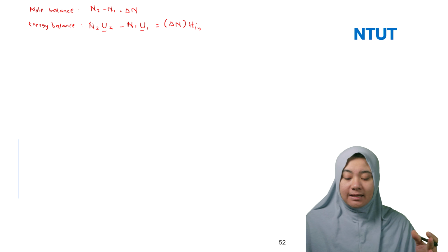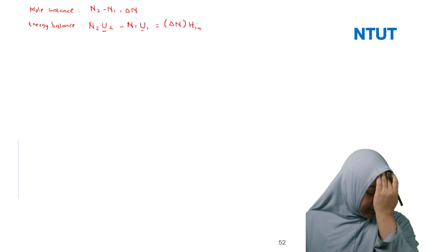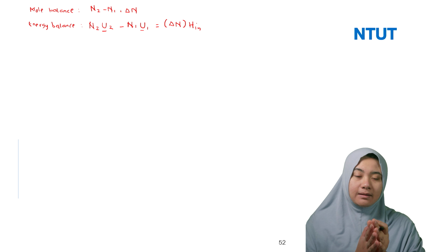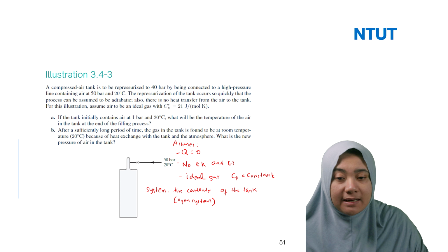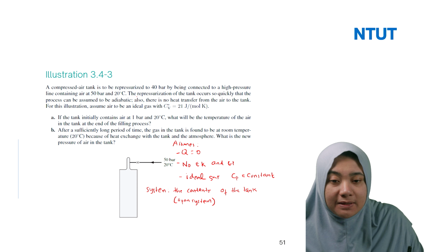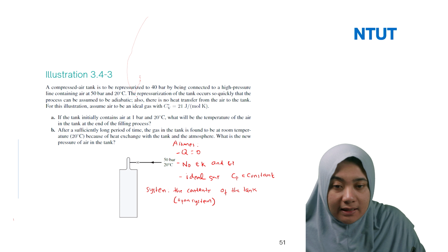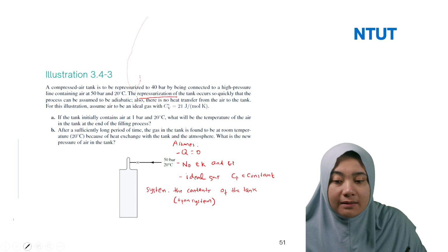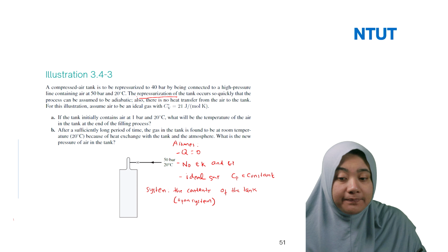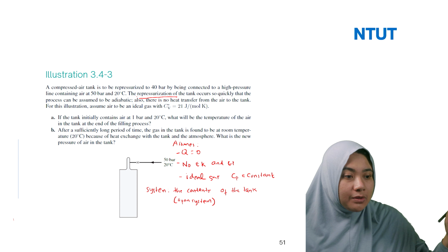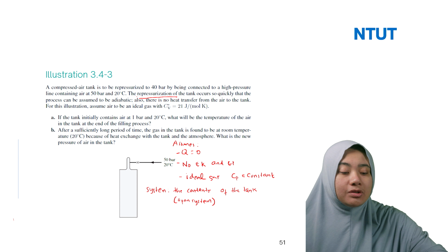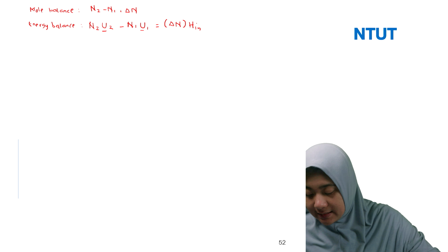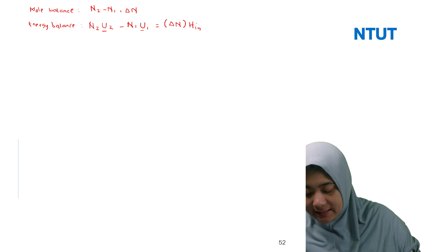Why is it H in here? I simplify by H in because the problem says the tank is undergoing repressurization. Repressurization means the system is too fast, the flow is really flowing so fast. So you can assume it should be an isenthalpic condition. So H in is equal to the H in.